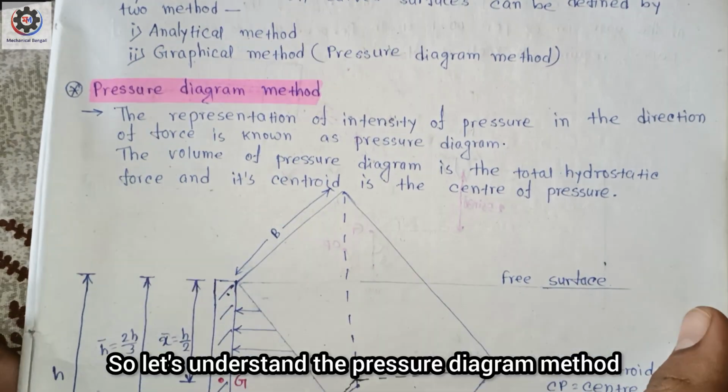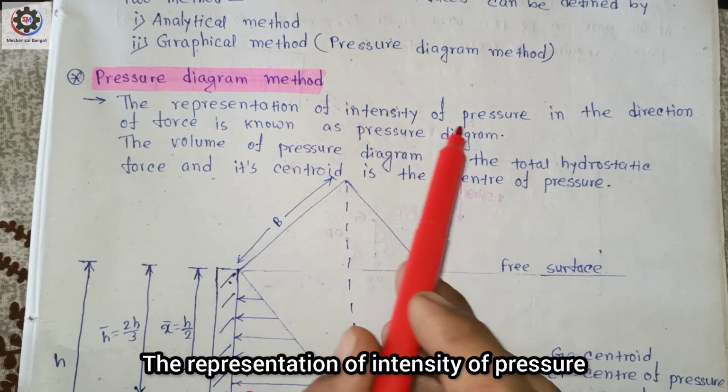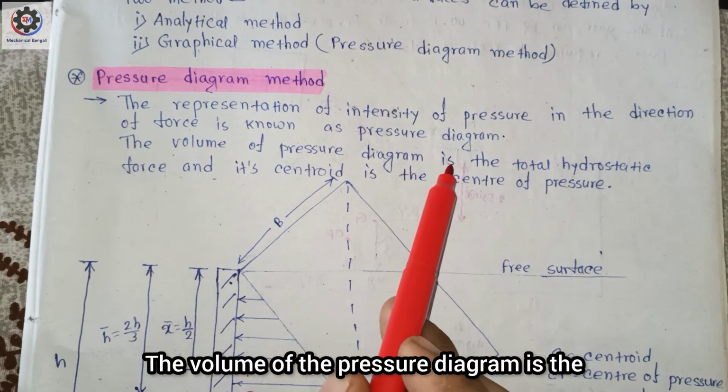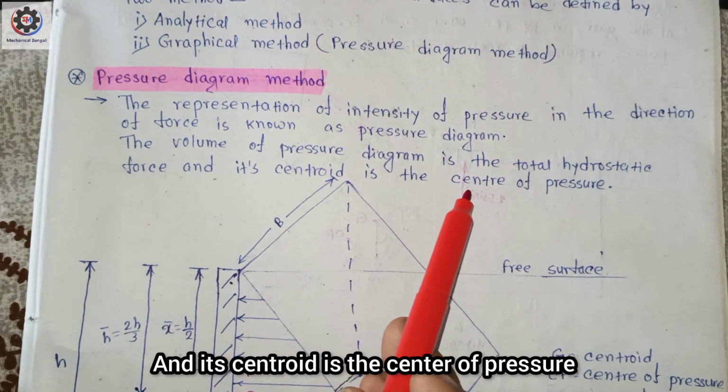So let's understand the pressure diagram method. The representation of intensity of pressure in the direction of force is known as a pressure diagram. The volume of the pressure diagram is the total hydrostatic force and its centroid is the center of pressure.